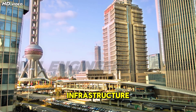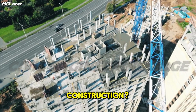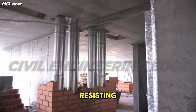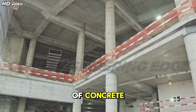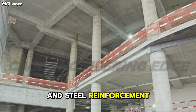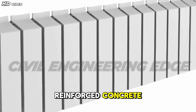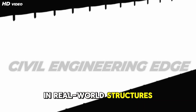What are reinforced concrete columns and why are they essential in construction? A reinforced concrete column is a vertical structural member designed primarily to carry compressive loads while also resisting bending moments and shear forces when present. It is composed of concrete, which performs exceptionally well in compression, and steel reinforcement, which provides tensile strength, ductility, and crack control. This composite action allows reinforced concrete columns to withstand complex loading conditions encountered in real-world structures.